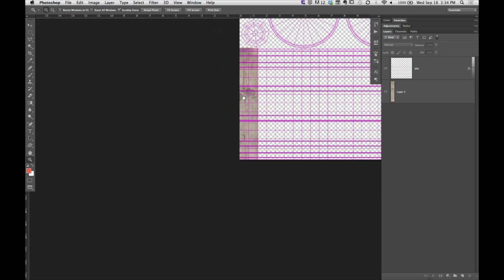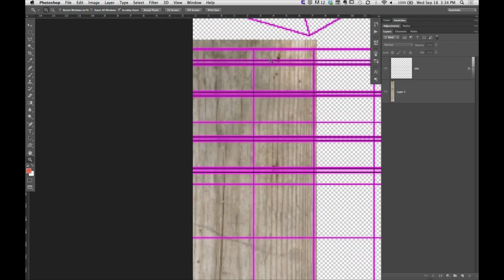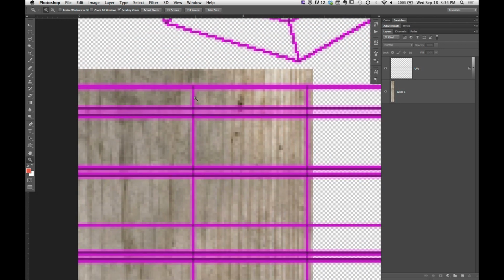And things are starting to look pretty good. Check this out. Is this allowed? Look at my wood plank texture in relationship to the borders of my UVs. Is this good? Am I cool here? No. Why not, Waddell? Because even though it's just off by a few inches, it's still going to overlap the other UVs when it's on the mesh. It's happened to me a couple times.